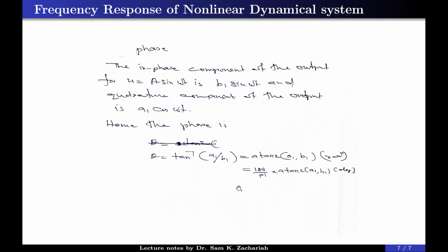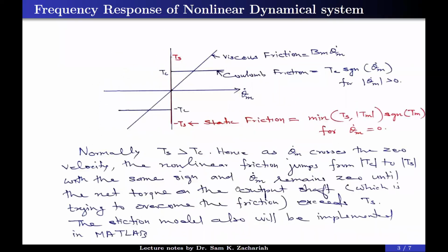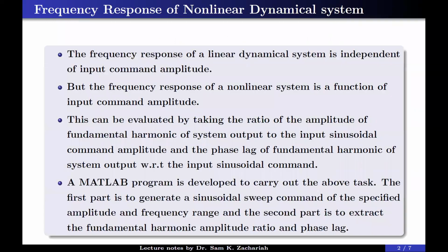So this is the theory for today's class. What we are going to do is frequency response. The frequency response of linear dynamics is independent of input command amplitude, but the frequency response of a nonlinear system is a function of input command amplitude. That you should remember. And this can be evaluated by taking the ratio of the amplitude of the fundamental harmonic of the system output to the input sinusoidal command amplitude, and the phase lag of the fundamental harmonic of the system output with respect to the input sinusoidal command.